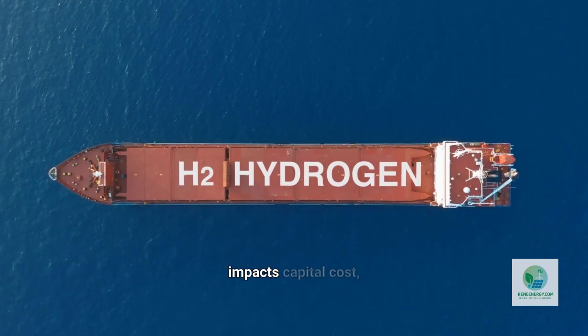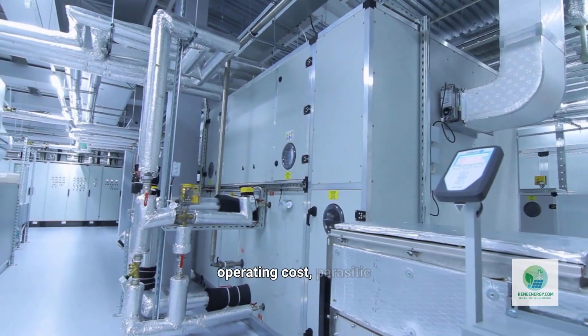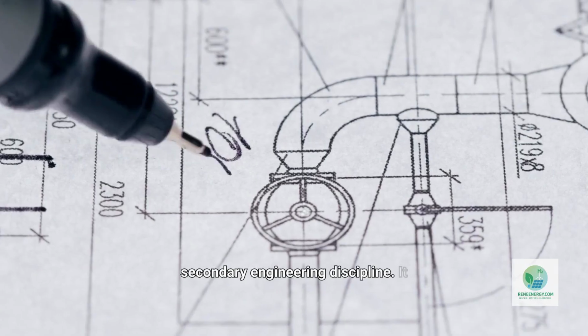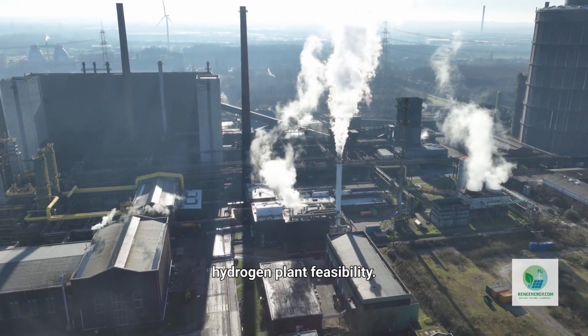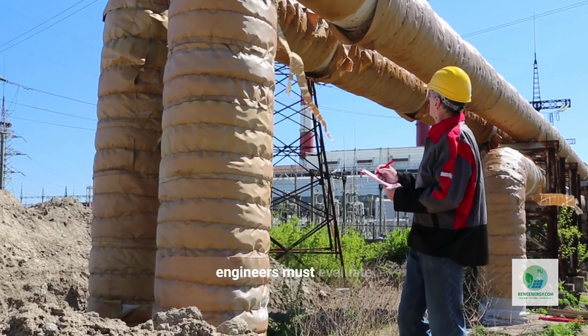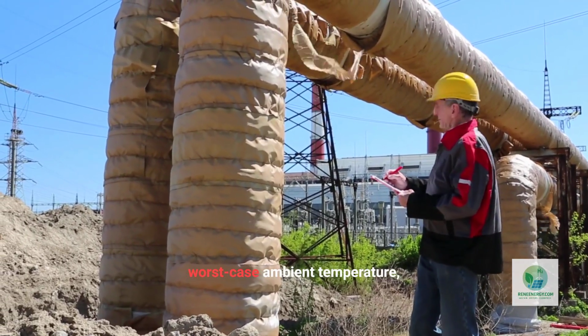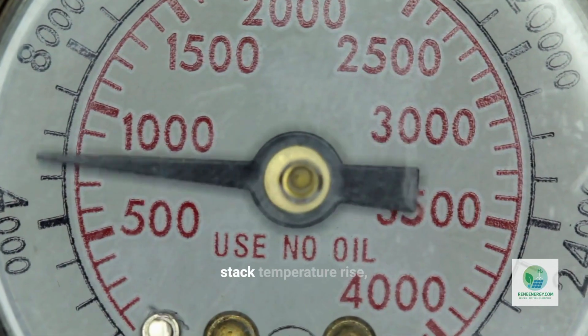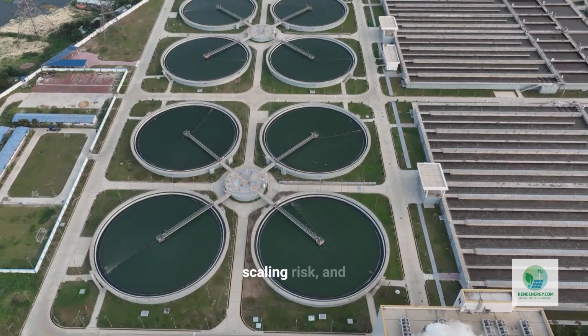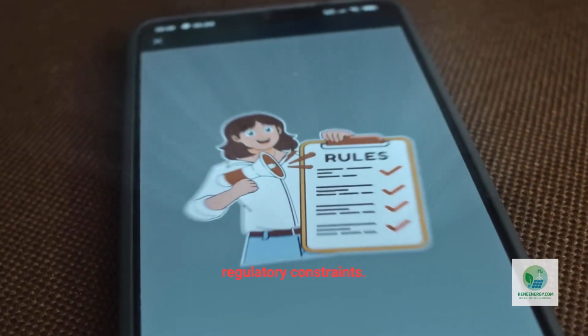Cooling design therefore impacts capital cost, operating cost, parasitic load, water demand, and stack lifetime. It is not a secondary engineering discipline. It is central to hydrogen plant feasibility. When designing an electrolyzer cooling system, engineers must evaluate worst-case ambient temperature, wet bulb temperature, allowable stack temperature rise, pump energy, water sourcing, scaling risk, and regulatory constraints.